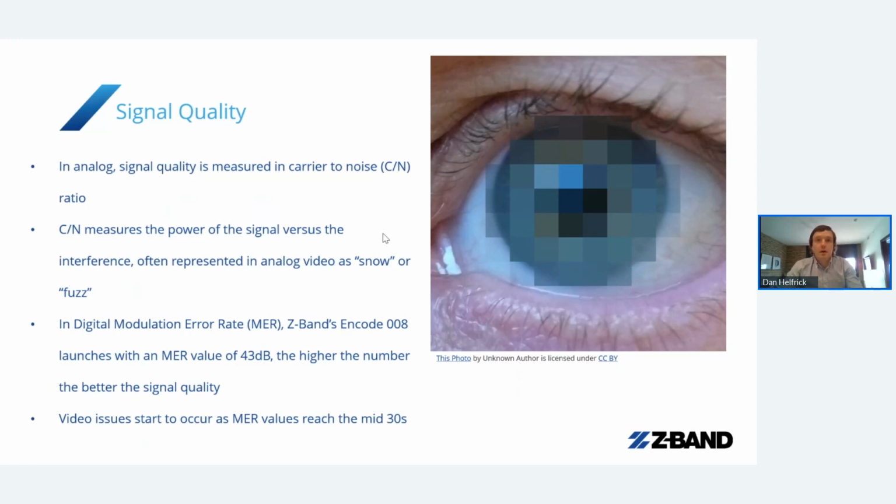With MER, that's a lot harder, right? Because I can't just put a device in front of the television and have it fix all of the errors that are injected into the system as it's made its way through the infrastructure to the TV. So you have to troubleshoot that MER. We have to figure out where exactly we're getting these video quality issues. Are we picking up some interference somewhere along the line? Do I have a piece of equipment failing? Do I have an amplifier somewhere that's jacked up to 60 dB on the output and that's blowing a bunch of noise into the system? And then when you find that, you're normally either adjusting or replacing whatever piece of equipment is the source of your problems to begin with.